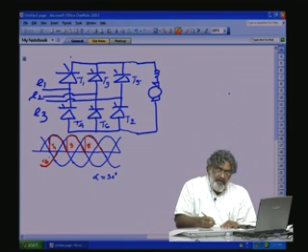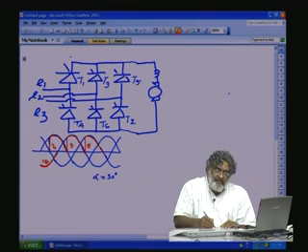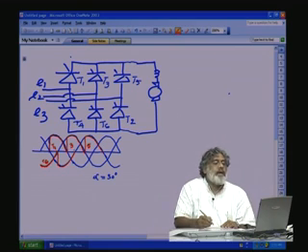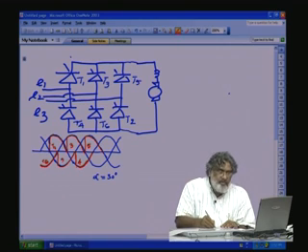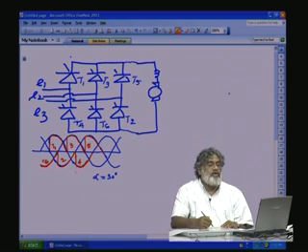Okay. Then after T6, this waveform is the E3 waveform. E3 going negative means T2 will be turned on. So, from here T2 will be turned on this way. At this point, when E1 is at maximum negative, here T4 will be turned on. So, it repeats like this. This is 4, this is 2 and this is 6. So, we have ripple voltage for the positive and ripple voltage for the negative.